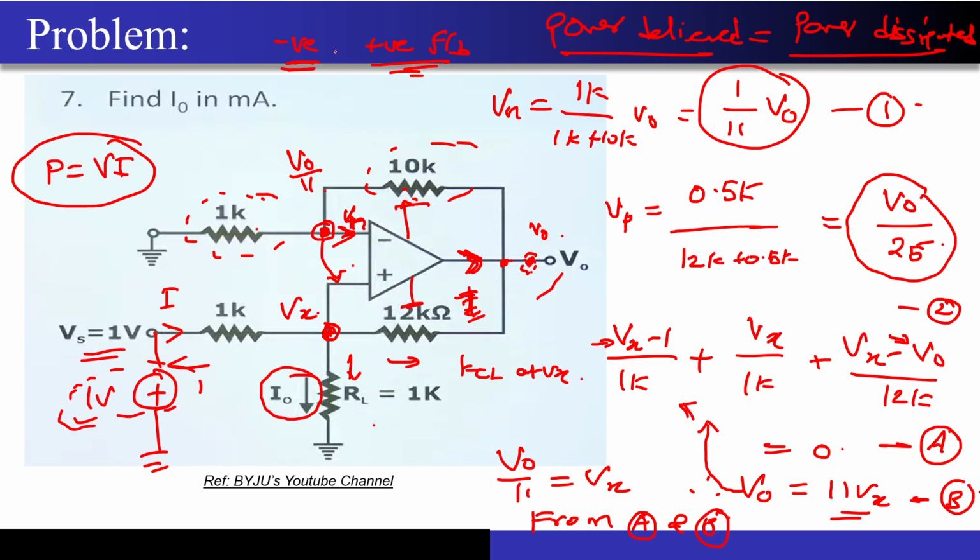The op amp has almost infinite gain, correct? Because it's an ideal op amp. And now you're operating in positive feedback. Normally we use circuits having positive feedback either in the Schmitt trigger or to construct oscillators, right? So the output voltage will actually grow and it will just saturate to the supply voltage, either the positive or negative. Or if there is some kind of hysteresis going on in the circuit like the Schmitt trigger, then you have upper and lower voltages already defined that the output can actually reach. So that is how I will answer the question.